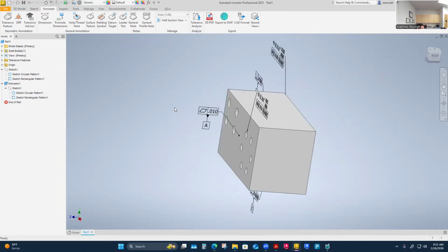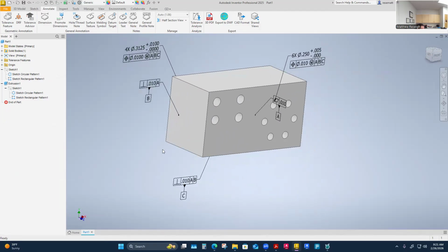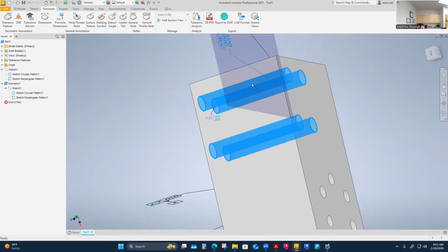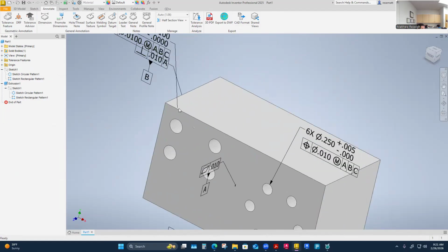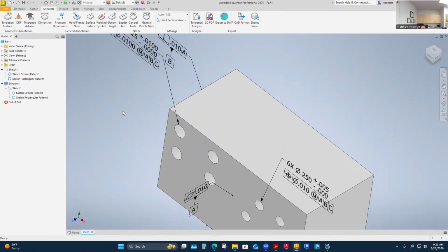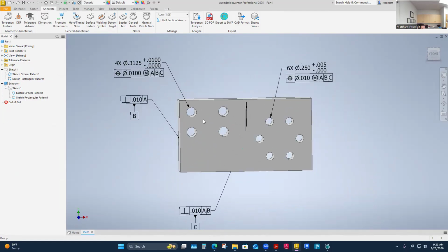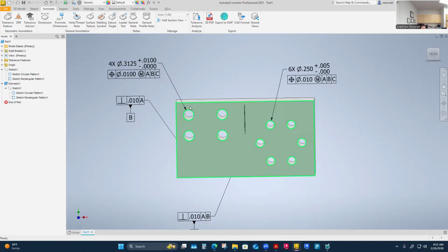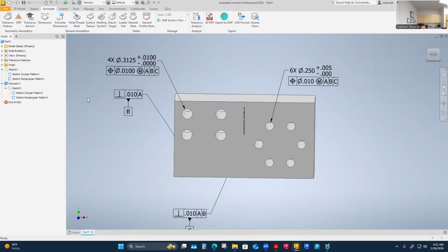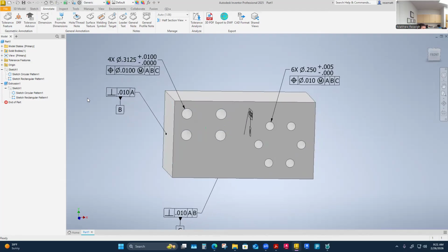One pattern arrow, the other pattern is like for that. Oh yeah, I think you can move these. I think they have grips on them that I could slide this to the front. And sometimes, if you're going to bring these annotations into a drawing, you might find yourself coming back in here, because I don't think that would have shown up great on the drawing. It might have been kind of weird the way the leader line points to that. Because you remember, if we go into a drawing, we have the option to say retrieve model annotations. And you may find yourself coming back to the model and slipping the leaders around so that they display correctly on your particular view on your drawing.